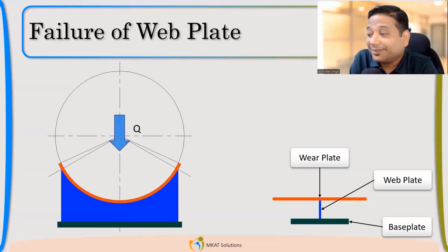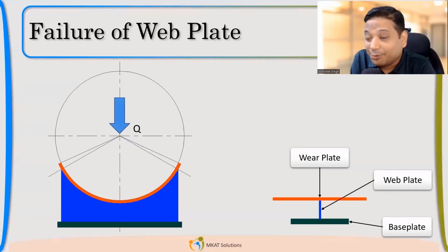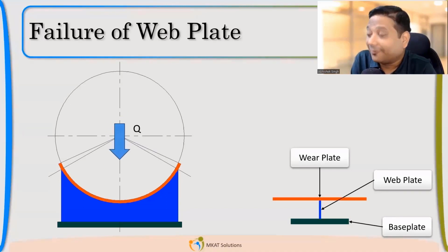So there will be longitudinal and transverse loads. Both longitudinal and transverse are horizontal, but they have a vertical component because there are two saddles, right? So if you are creating a moment, to counter that moment there is a reaction load. Anyway, we have spoken about that in the earlier chapter where we did the Zick analysis. Great. So that is the load which will be coming on the saddle. So we are very clear about the load.